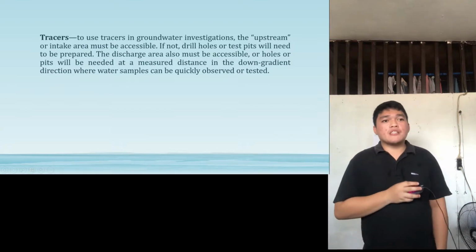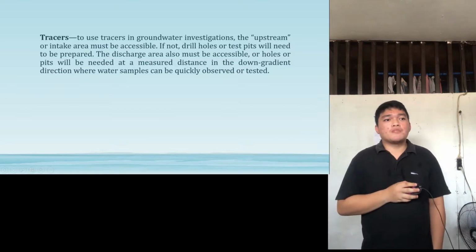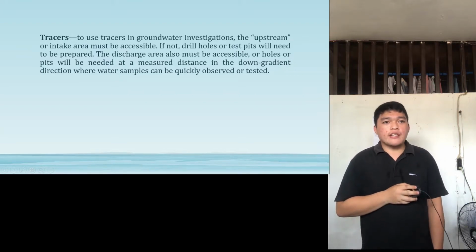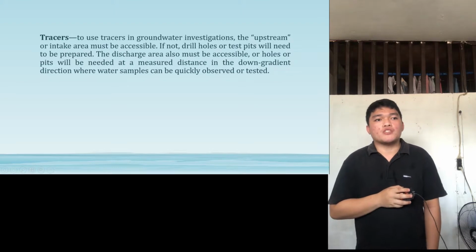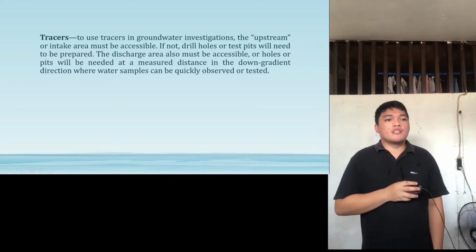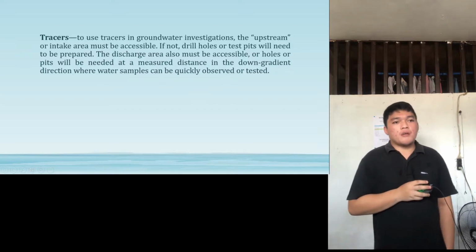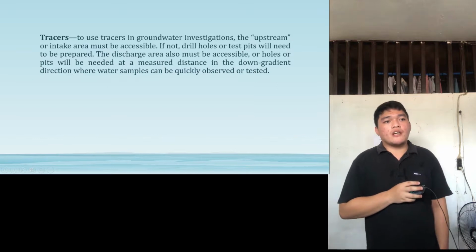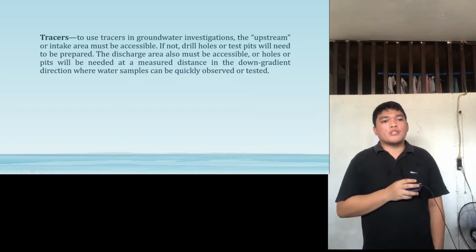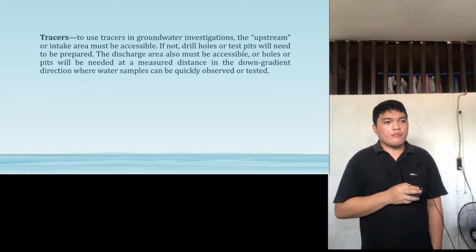To use tracers in groundwater investigations, the upstream or intake area must be accessible. If not, drill holes or test pits will need to be prepared. The discharge area also must be accessible, or holes or pits will be needed at a measured distance in the down gradient direction where water samples can be quickly observed or tested.